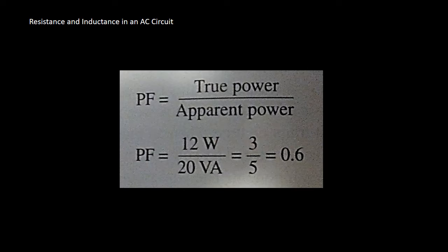The power factor is not only considered in theory, but in practice. The power factor must be considered whenever a power company connects power lines to a manufacturing plant. Industries must keep the power factor of their circuits and machinery within specified limits, or pay the power company a premium. The reactive power is sometimes called wattless power. It is returned to the circuit.